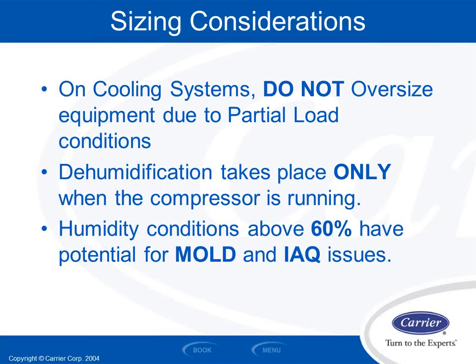Other things we can do to more actively dehumidify the system, other than correctly sizing the equipment, which we should always do: multiple stages of equipment is very beneficial. The more stages, the better, generally speaking. If I have one stage equipment, which basically means I turn the compressor on and that's it, and I get whatever I get, that's fine when it's 92, 95 degrees outside. But when it's 78, 80, 83 degrees outside, I don't need as much cooling. So I'd like to have multiple stages so I can only put on what I need.